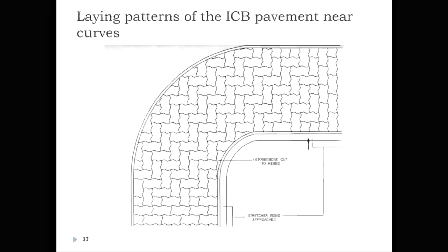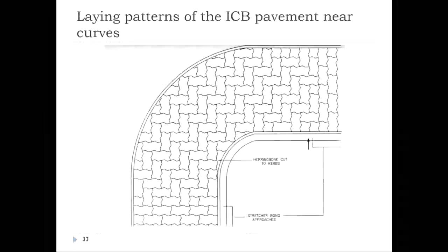Now regarding the laying pattern, especially on curves, you will find people adopting a different laying pattern. You can see up to here they have been adopting a stretcher bond pattern, and you would be finding a herringbone pattern when it comes to the curved areas.